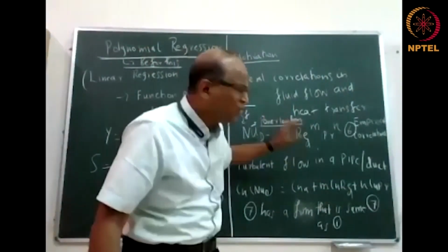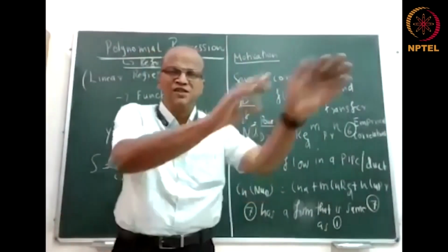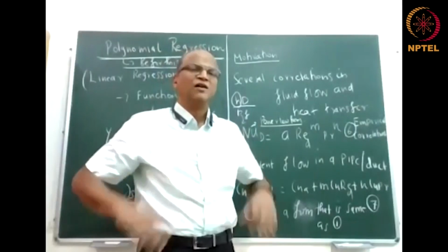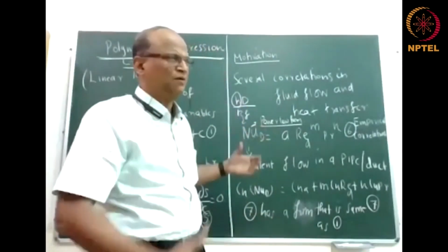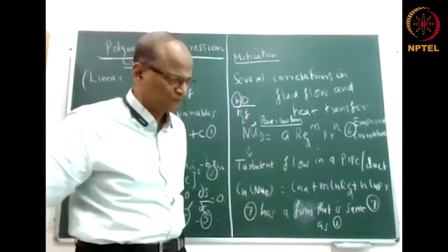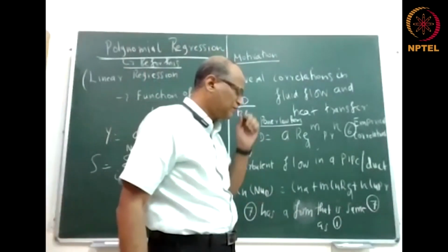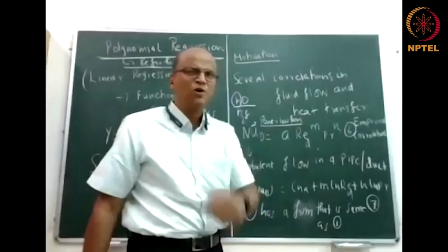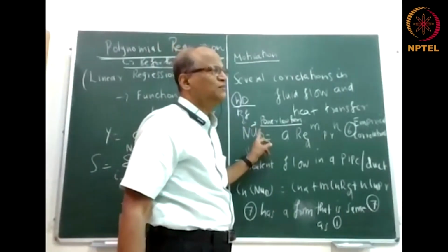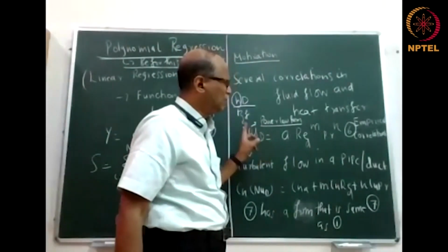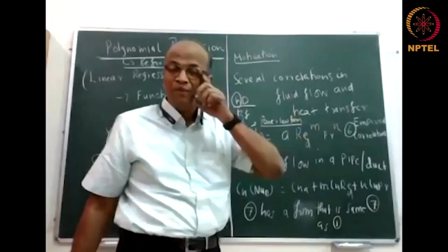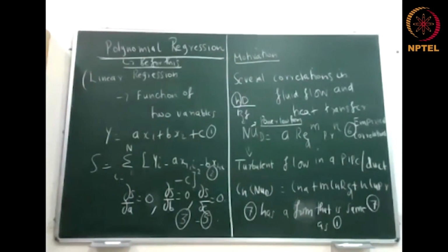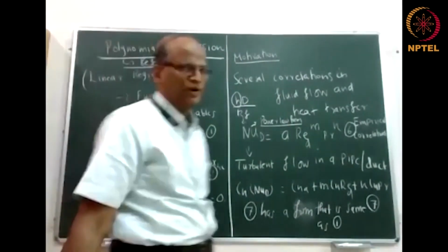So how to get this form? Either you should put in the theory or get it from literature, or you should be able to do a Buckingham pi theorem, write in terms of dimensions and find out what are the governing parameters. That is the second approach. The third approach would be to take the original governing equations and keep on normalizing them. If you keep normalizing them, you will hit a point where the Reynolds number and Prandtl number will automatically come into the picture.